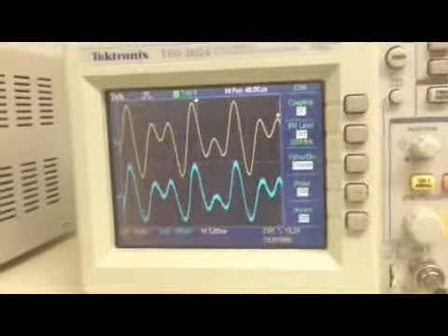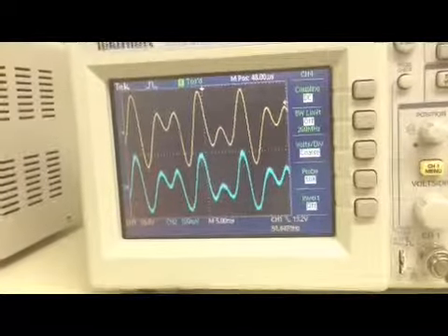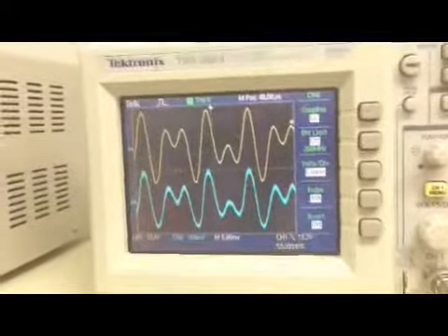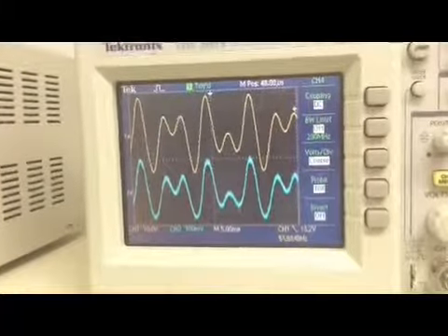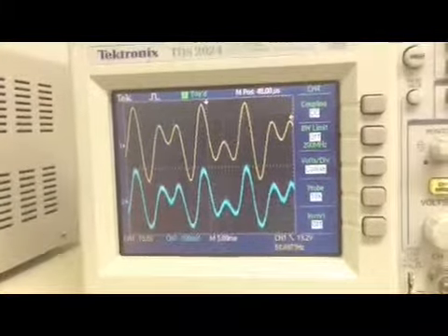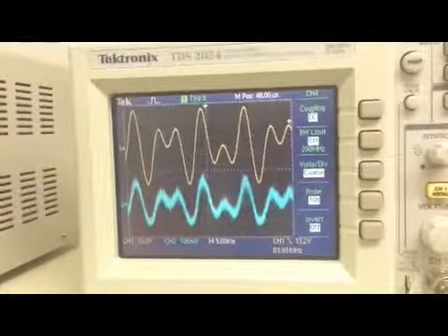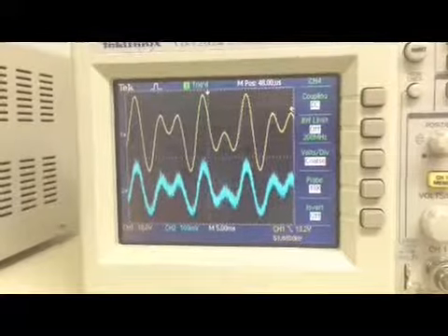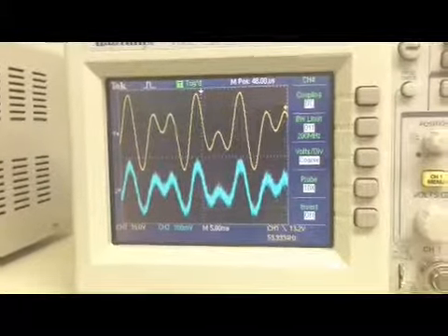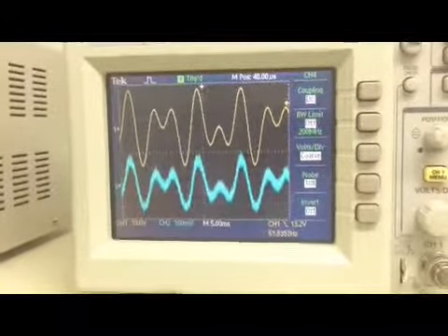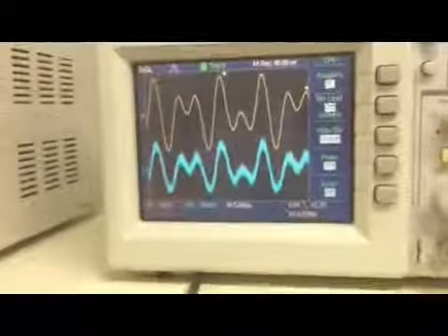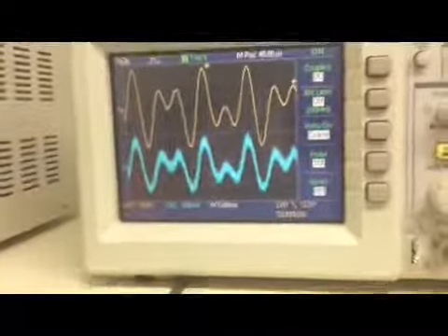So the input signal that we have right now is minus 50 dBm, and as you can see, it looks pretty darn good. No real distortion on the signal, operating within expected parameters. We take it down to minus 85 dBm. There is quite a bit more noise, but there is filtering that's installed in the main board, so we should be able to filter all that excess noise out and have a good looking signal.